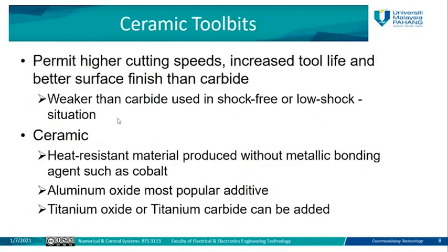The third type is the ceramic tool bits, which permit higher cutting speed, increased tool life, and better surface finish. In order to understand the benefit of using that tool, or the difference between these types of tools, as a CNC machine operator you need to refer to the user manual or the catalog provided with the CNC machine, or maybe with the automatic tool changer.